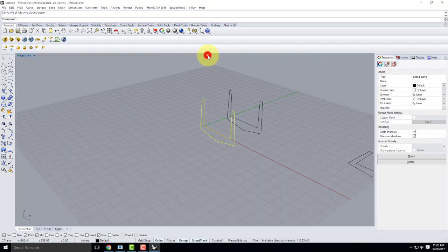We're working in the perspective view, so chances are your offset is going to work as long as the In C-plane option is set to yes. I will explain at much greater length later on in the semester what C-planes are and why they're useful. But for right now, we don't need to worry about C-planes. It's a little bit too complicated for where you are. So from here, I say in step 3 to go ahead and explode these two objects.